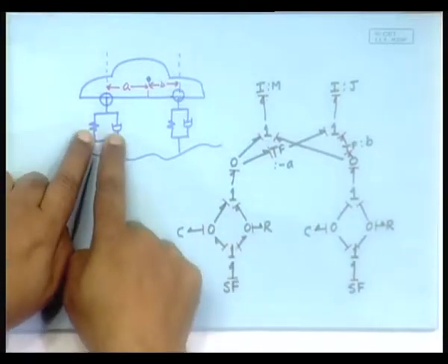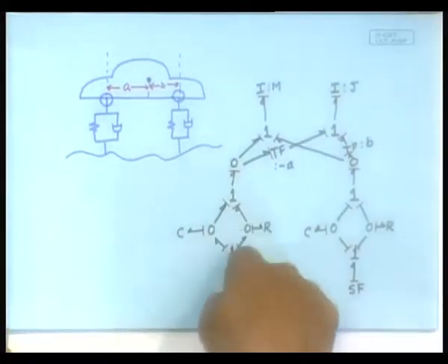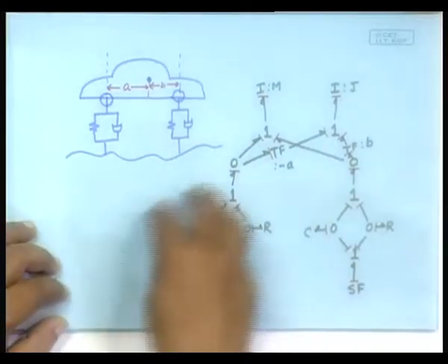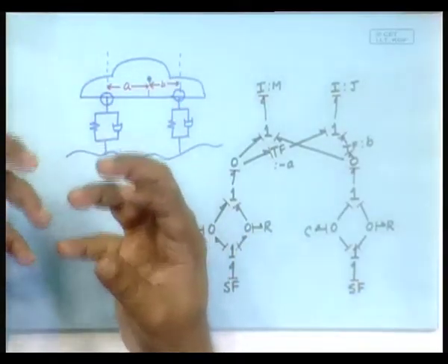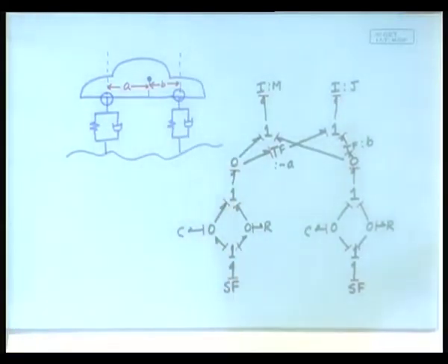This spring damper arrangement, as a sort of cushion, is a unit that can be abbreviated with one bond going up and one bond going down. So that later all this can be put as one element, but that comes later. First you have to understand this, but then you will see that there are many things that come as a unit, and that unit has a specific characteristic given by two extremity bonds.